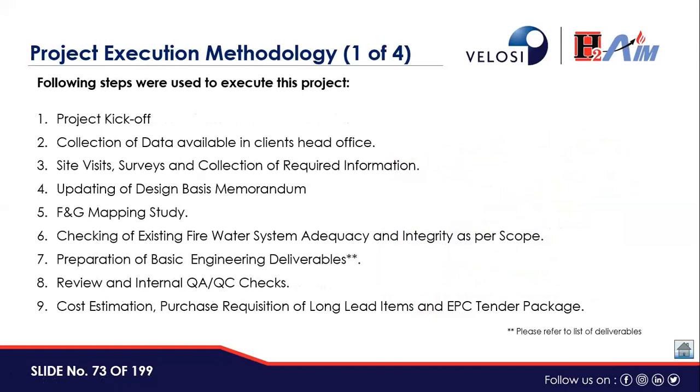And this is the execution methodology. We executed this project by following these steps. The project starts with the kickoff meeting, then the collection of data, site surveys and site visits, collection of required information, and then the updating of the design basis memorandum. Then we performed the F&G mapping study. Then we checked the existing firewater system adequacy and integrity as per the scope. And then we prepared the engineering deliverables. We will discuss what the deliverables were, and then